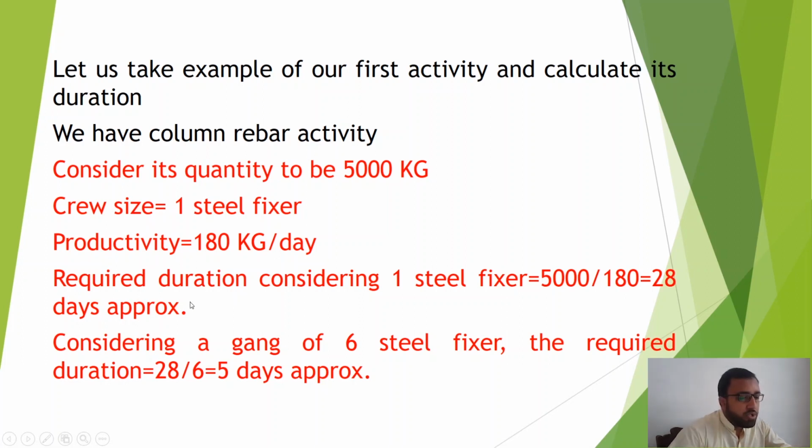So the required duration, considering 1 steel fixer, is 5000 divided by 180, which is equal to approximately 28 days. So obviously we are not going to put 1 steel fixer for that activity. Obviously we will put some 6 steel fixers, or 12, or 15, based on our requirement.